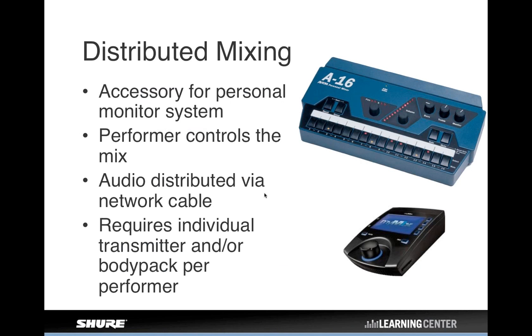How these systems work, there's a couple of different ways. These ones that are shown here, typically all the microphone signals get connected to a head end of the system, where the mic signals are digitized and distributed out to these pods via network cable, like Cat5 cable. That's basically how these systems interconnect. And then the signals arrive digitally at these locations where you can make your mix adjustments. There are also some digital mixers now available that allow you to mix off of iPads. So you can have a Wi-Fi router that connects to your mixing console, and all your iPads are linked to that router, and you run a little app on the iPad that allows you to create your monitor mix right there.